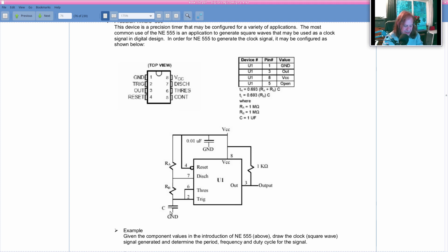If you're a double E student, you'll do a lot of design with capacitors when you start working with filters and oscillators and so on. For us, we're just going to take a capacitor, connect between pin 2 and ground. And then pin 4 gets connected to pin 8. That's the reset line. It's got a bubble on it. So if we put a 0 in here, the circuit gets reset, nothing happens. So we want to connect this directly to 5 volts, through connected to pin 8.